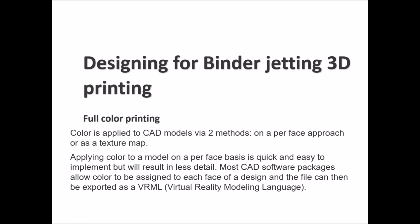Usually the color application is done through your CAD software, where you designed your parts, in two methods. Either you do it per face or as a texture map. So it means either you choose each face of your part and assign a certain color to it, or you bring your own texture or image and apply it on the part through the software. If you apply the color to the model per face, then this will be easy and quick to implement, but it will give you less detail of colors and less vibrancy.